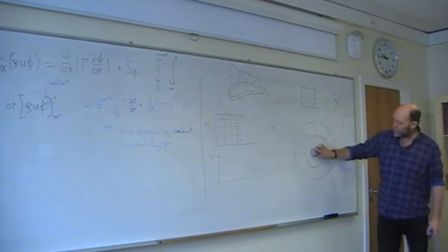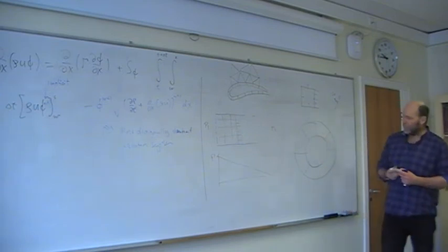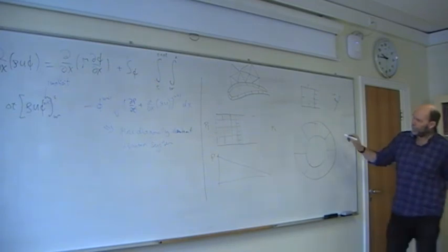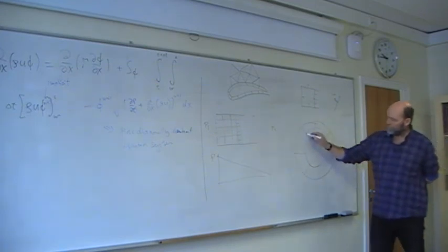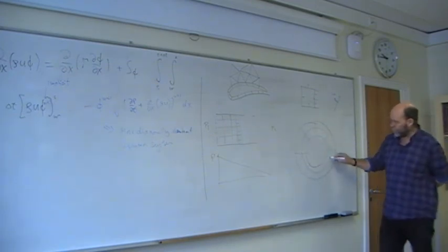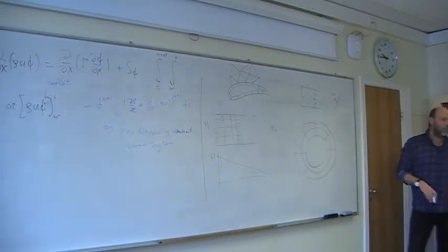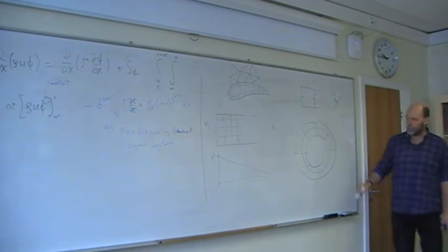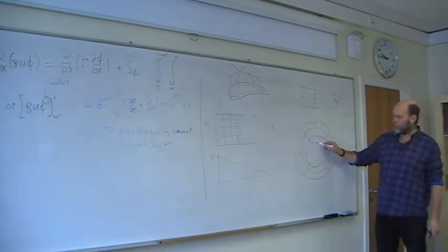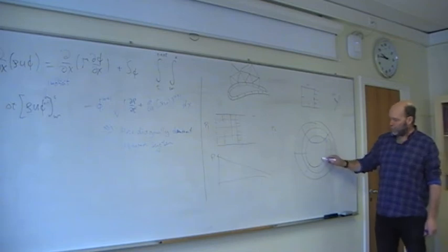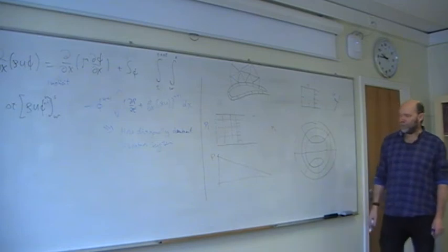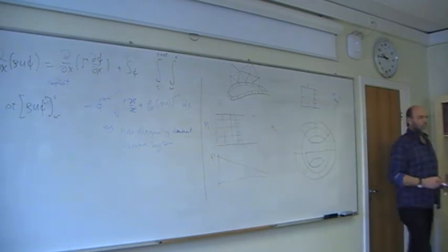Well, you can use cylindrical coordinates here towards the inner surface of your pipe. That's okay. But in the center, you switch. Use an unstructured mesh or some hybrid mesh or something, so you sort of end up with a more or less rectangular mesh system in the center, or else you're dead.